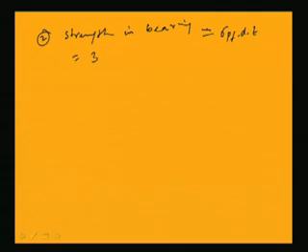Similarly, strength in bearing will be sigma Pf into d into t. So, for power driven shop rivet sigma Pf value will be 300, here d is 23.5 and t is the thickness.